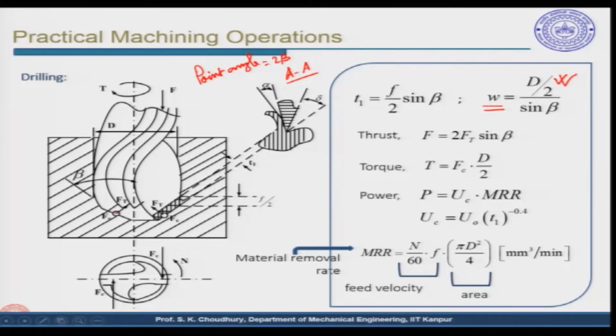Fc will be like this, it is visible in other view, and here therefore, it will be as a cross and a dot. So, here you can see that this is Fc, which will be withstood by the torque given to the tool. So, this is resistance to the torque given. Therefore, it is in another direction, as you can see. So, this is the Fc and this is the Ft direction.